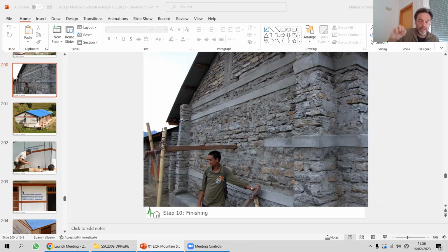I have to say that there has been some research done about whether the tooth is needed, yes or no. What I understood is that it is quite essential in the overall working of the shear panel and how this frame connects to the wall. And it's not so difficult to do anyway. It seems to have advantage, but I also know that some more research is being done on this. Does that answer the question?